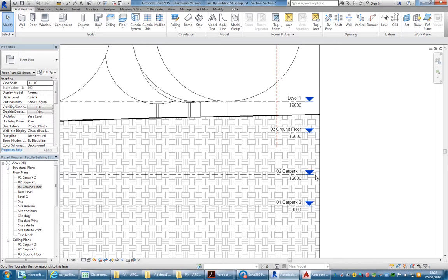You'll see there's a lot of the setup in Revit files is based around floor-to-floor levels. So you'll see things like the view setups are based around the idea of a view that is looking up to the next level. And so if you put a ceiling level in the way, the view's going to stop there. So a ceiling plan, for example, is going to stop at your ceiling level instead of looking and seeing everything that's in the ceiling, and you have to go and then adjust it. So I just like to work with the defaults. It just is the least effort usually.